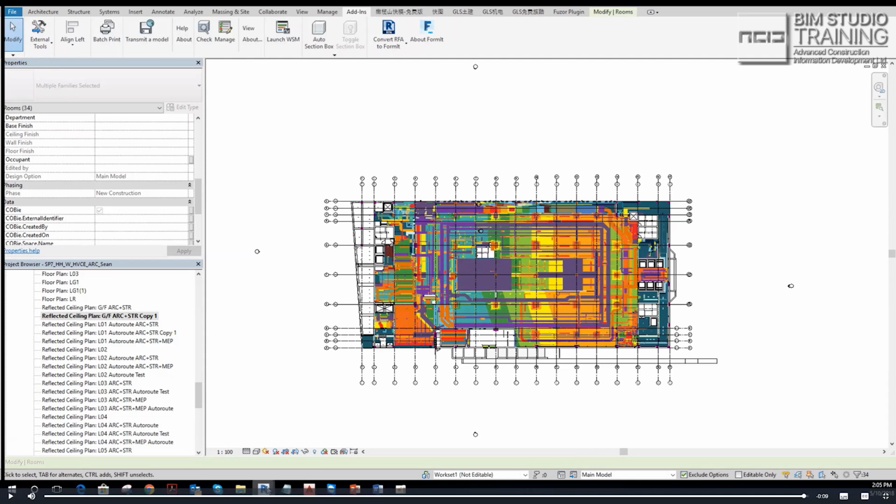Clash avoidance. Now, this is step one. This is my initial detection. No surfaces, just ceiling and beam. Then after I run the first pipe, and I run the software again, it becomes a different heat map. So the leftover space for my second pipe, and then run again the third pipe, and run again, keep on running this. So I'm doing a clash avoidance approach. There's no clash.